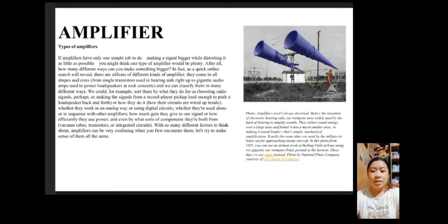The first is the voltage amplifier. This type of amplifier is designed to amplify a given voltage to yield a larger voltage output. So it involves low output impedance and high input impedance. Low output impedance is desired so as to draw maximum current from the circuit. And high input impedance places very little load on the signal that is being amplified.